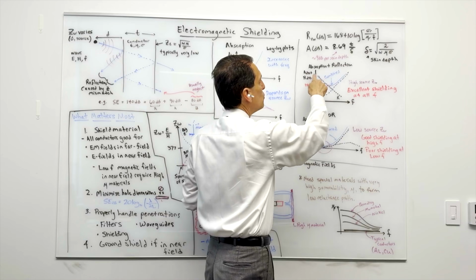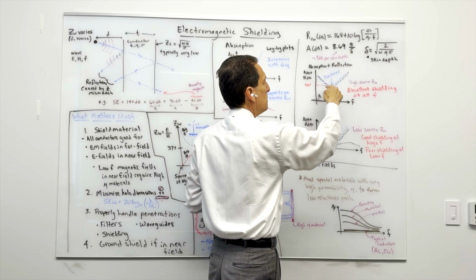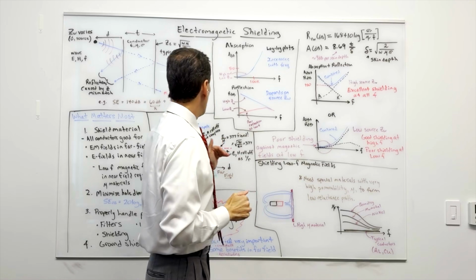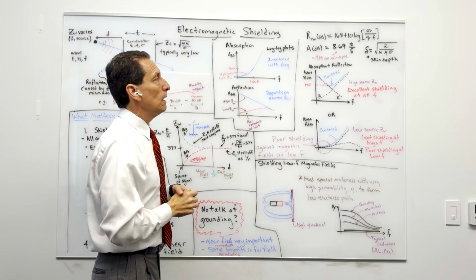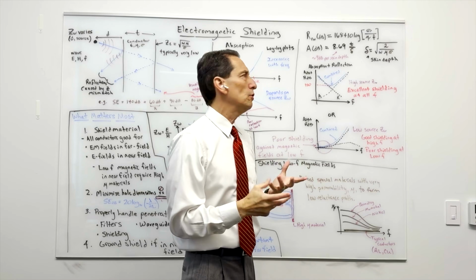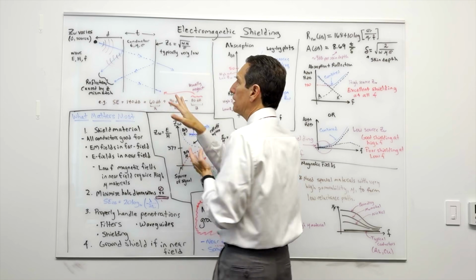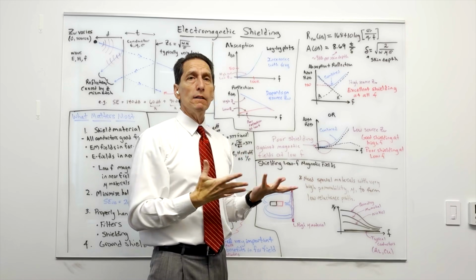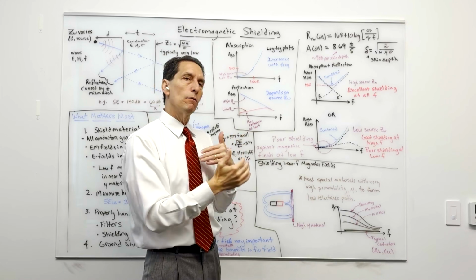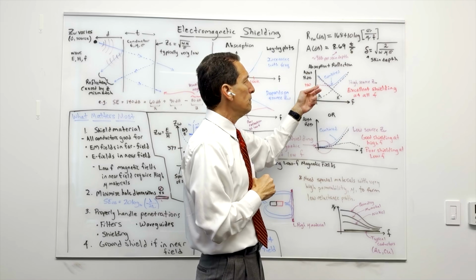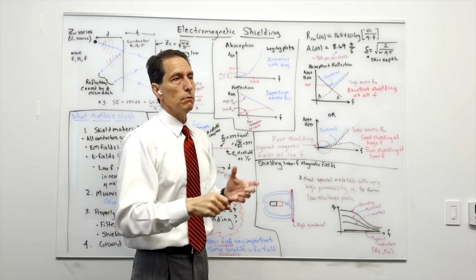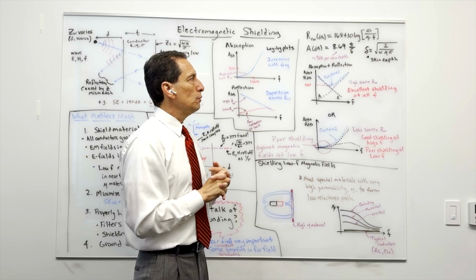It says, hey, I get really, really good combined shielding at low frequencies. It kind of dips down in the middle frequency range, and then it goes back up at the high frequencies. So you get excellent shielding at all frequencies when you have a high wave impedance like a monopole type emission here. There's no real concerns. You can get very, very large shielding values. And in fact, it really doesn't get dominated by the conductor anymore. It's by the flaws in your shielding, maybe you have gaps or seams or holes, and that ends up dominating the shielding effectiveness, not the fundamental limiting aspects of your absorption and your reflection. These numbers are very high, maybe 150 dB and up, and it's very difficult to actually achieve 150 dB in real practice because of the imperfections of your shield, like the lid, the door, whatever you had to add to your shielded enclosure.